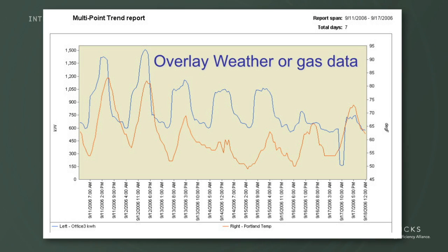Now in this instance, this is a week, so this is your Monday, Tuesday, Wednesday, Thursday, Friday, and your Saturday and Sunday usage is a lot lower. This is typical of an office building that's used mainly Monday through Friday, with the weekend being at its lowest value when things are shut off. In this case here, the energy usage dropped from about 600 kW down to 150 kW for approximately an hour. A lot of times you may see that because some facilities have a backup generator they may run and they may be testing it. That usually is done on Sundays.